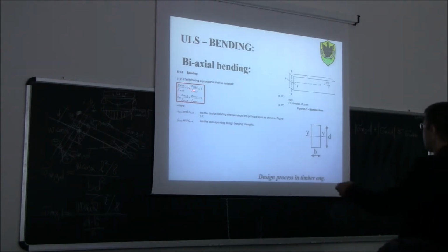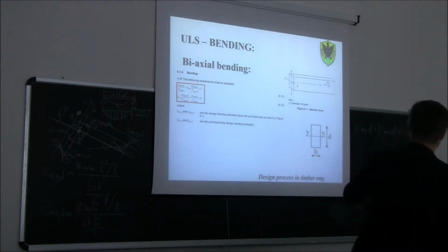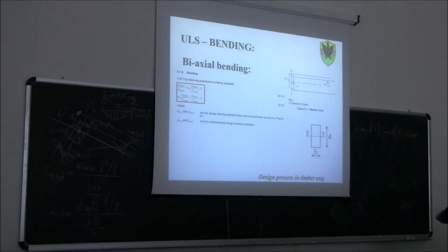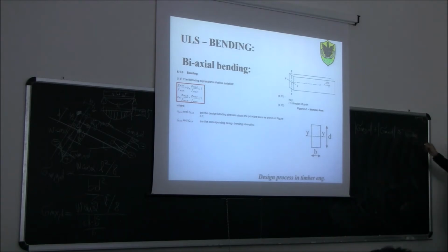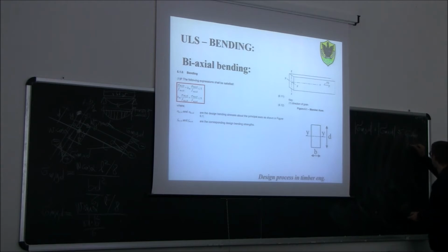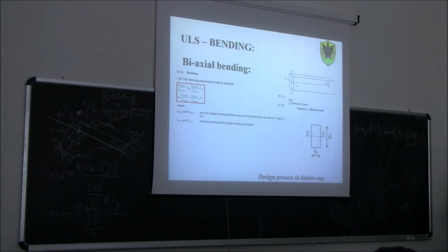So we don't sum up the two of them and we compare, of course, in this case, we shouldn't compare with sigma admissible stress. We should compare those two stresses with f m d, right? With the design bending strength. In this case, because we're not talking about the permissible stress method, we're talking about the semi-probabilistic method. So we should check with the design strength.